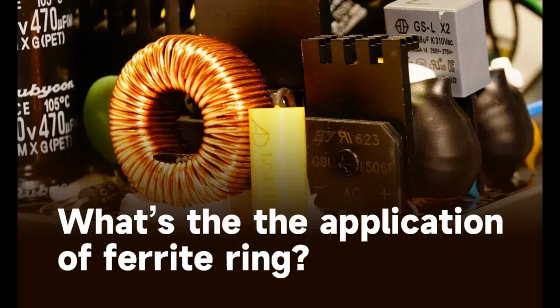1. Power supplies. A. Switch mode power supplies, SMPS. Role. Ferrite core inductors are used in SMPS to filter and regulate voltage. They store energy during one part of the switching cycle and release it during another, helping to smooth out voltage fluctuations and reduce ripple. Benefit. High-frequency operation and reduced energy losses make ferrite core inductors ideal for efficient power conversion and regulation.